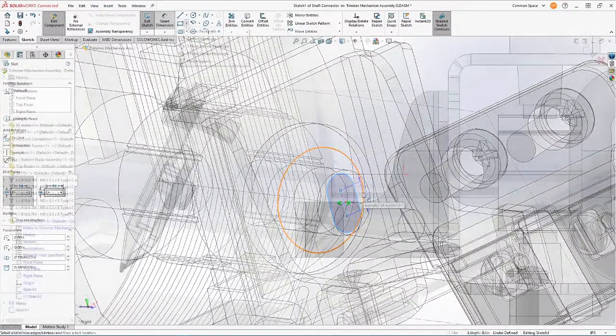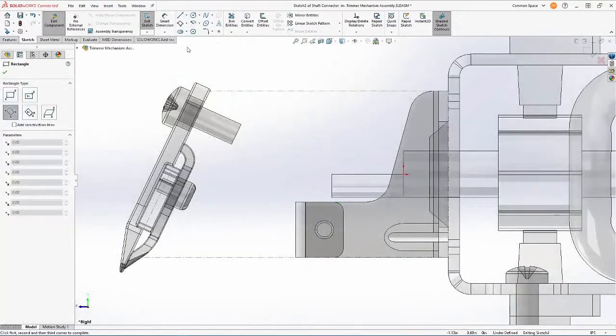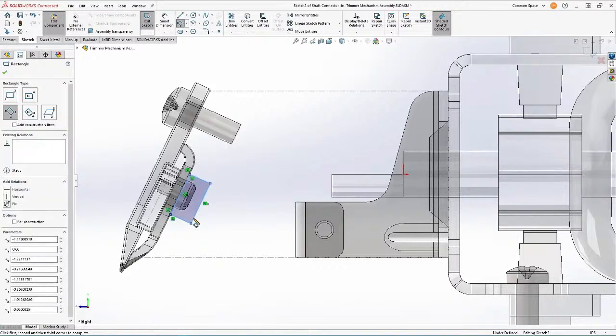Let's keep it going. Alrighty, so the next sketch will be the side profile. And what I'm actually going to do is attach the sketch to the bottom blade. That way, if I adjust the orientation of the blade later on down the road, my component will update with it. So this is just best overall design intent to avoid making unnecessary changes later down the line.